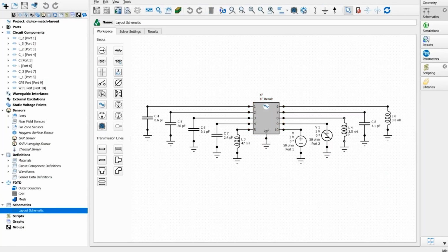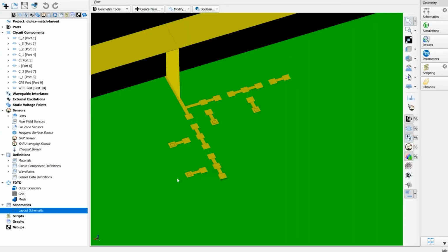So whenever we change the inductance value or the capacitance value, we're considering the matching network parasitics and all of the full wave effects in our results. And so the same idea of having design goals, allowable component values, looking at S parameter isolation or system efficiency results, having tuning sliders, and optimization, all of those features are still available in this type of setup. It just so happens in this case we're analyzing this full geometry whenever we're deciding on our component values.